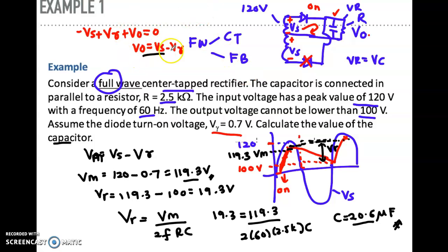So in this equation, here we don't denote directly V out, we denote here Vm, because this Vm is the voltage after the diode, right, the maximum. And then when it starts to discharge, this area, the diode will be off, and the capacitor starts to discharge and charge again, discharge and charge again.